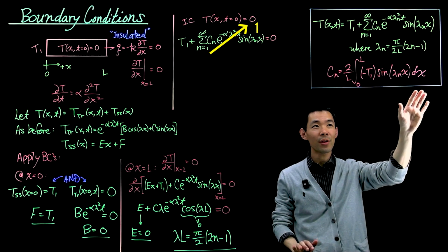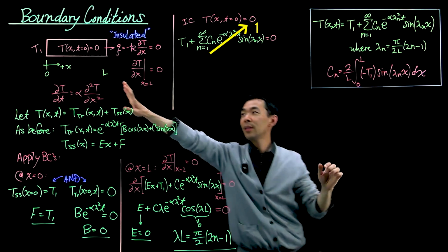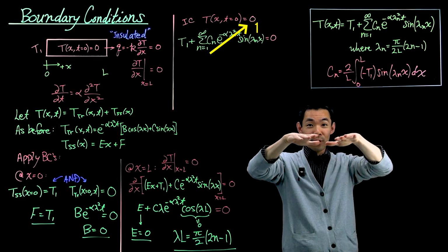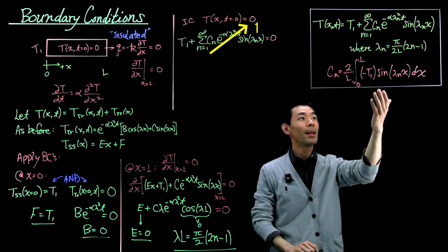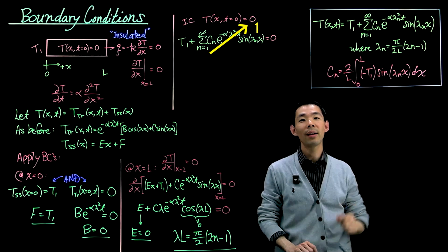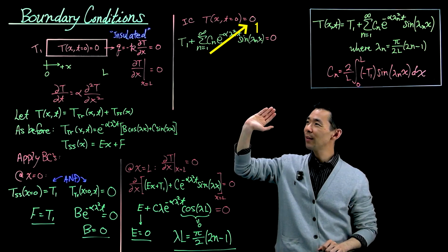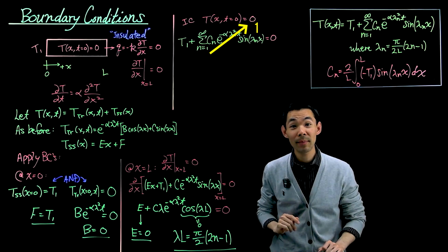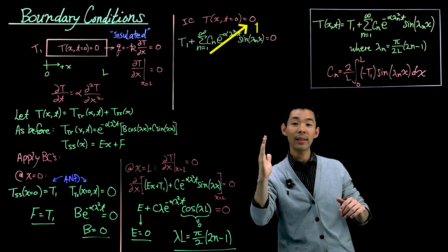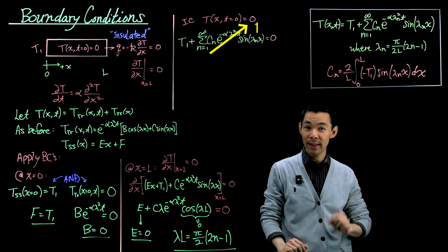It's just the usual definition where we're just taking the Fourier series of the function negative t1, which is the left-hand reservoir boundary condition that penetrates all the way through at steady state. We expect the temperature profile to be t1 all the way across. Multiply it against the sine series with the eigenvalues given by this expression right here. So this is it. This is the solution of the temperature profile inside this material for the condition where it's 0 temperature, left-hand boundary instantaneously increased to T1, the right-hand boundary always 0 flux, 0 heat leaving that boundary.